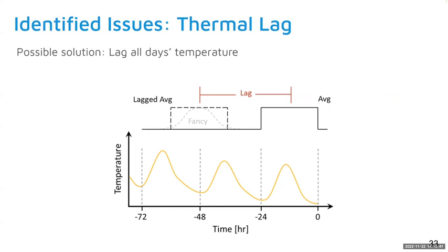And then you might have to devise a process that you could repeat after an energy conservation measure has been put in place, because the lag is likely to change after that point. It is likely to change. However, the entire point of what we're doing is not to anticipate a change. It is to be able to properly predict the baseline into the future. So we don't actually want to change the building's lag, because we want to see how the building changes when you increase the amount of insulation, for example.